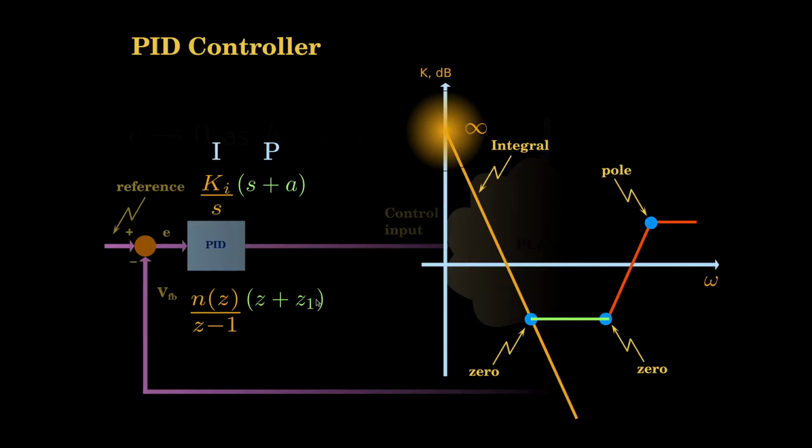So when you look at the digital PI, we saw in the I control just previously that there is a pole at z is equal to 1. If we incorporate a 0 at z is equal to some value in the unit circle, then GC will have the structure of a PI controller. So let us try to do that. We will attempt a PI controller for the same plant and see what happens.